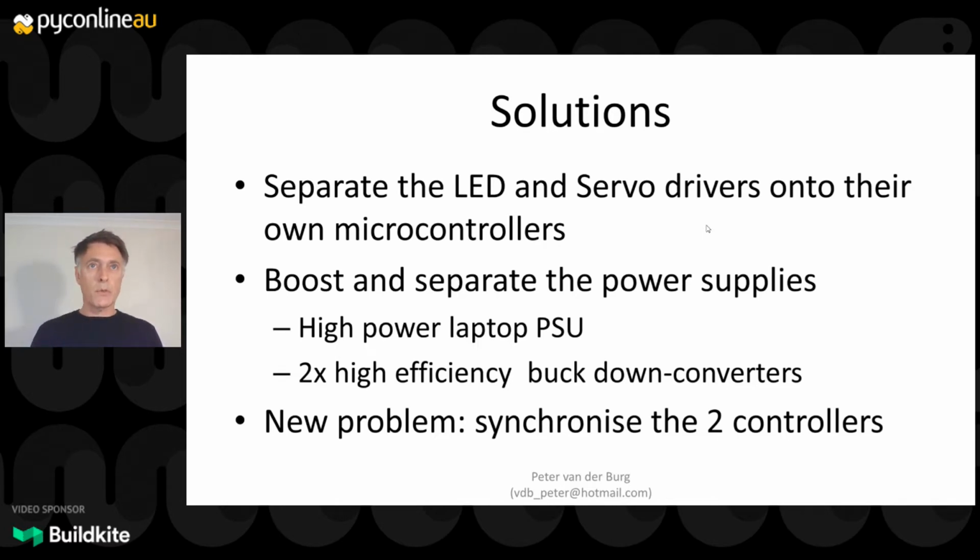So while the voltages were fine, the instantaneous current demand from especially the servo and the LEDs was too high for the original power pack. And so with a laptop power supply with lots of power, truckloads of power, and a couple of high efficiency buck converters, I managed to solve that problem.